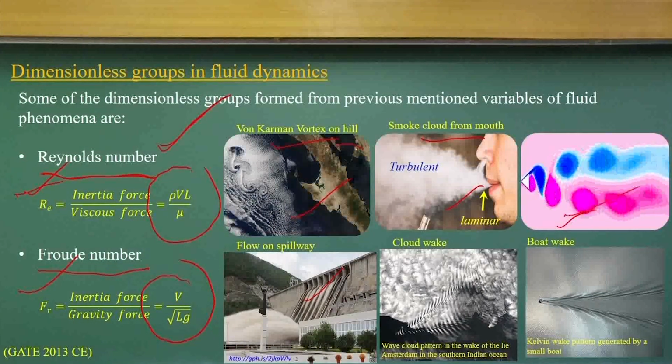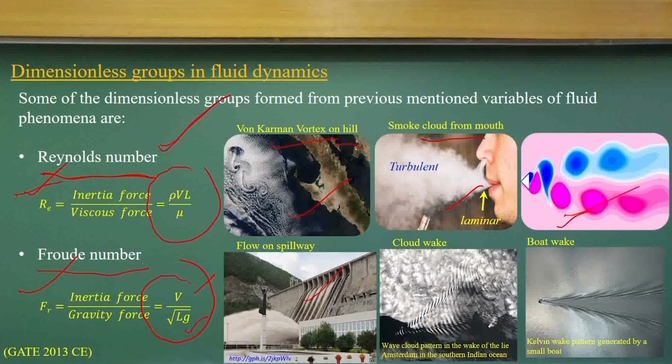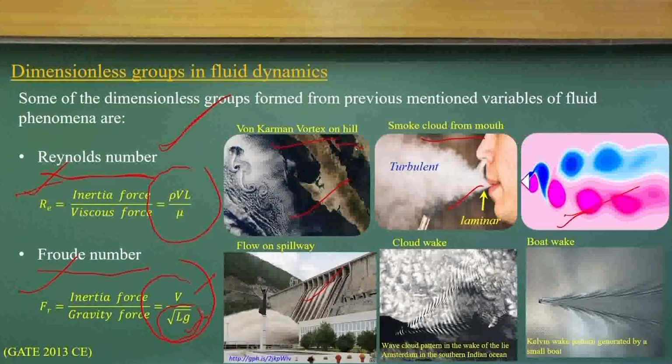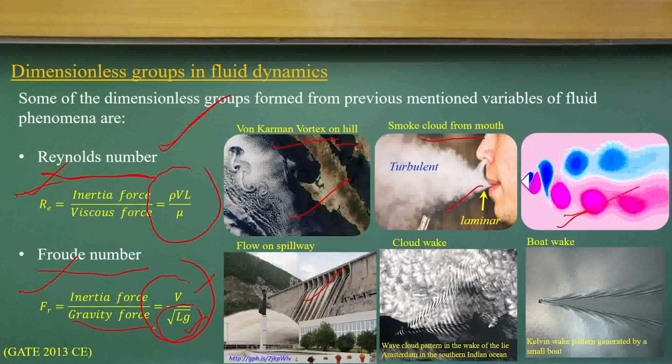That's what is defined by this as a non-dimensional form. So if you look at this, it is the velocity, length into g, square root, also the unit dimensions of the velocity. So it becomes non-dimensional. How to get this component, I think in these basic lectures I cannot complete that wave celerity concept here, but I will tell it in higher classes. If you go for postgraduate or open channel flow, definitely you will know how this square root of Lg comes as a gravity force component.